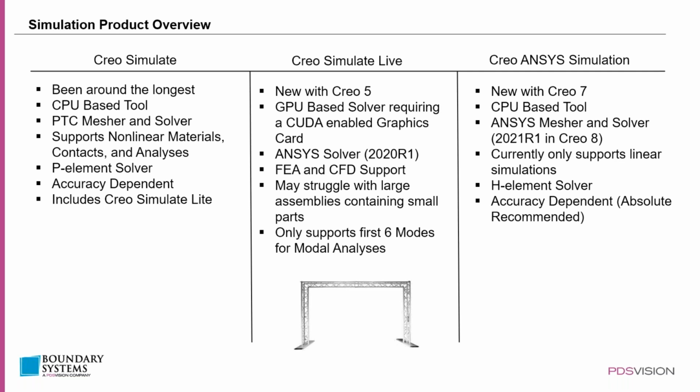So Simulate Live, again, pretty new. The main difference here is that this is actually a meshless solver. So it does not use a mesh. It does use an ANSYS solver. So it's supported by ANSYS technology, kind of behind the scenes. And the main benefit here is that it's going to run much, much faster than either of the other two